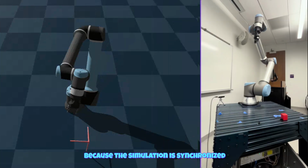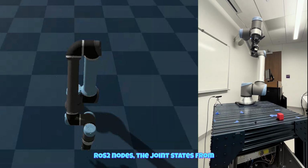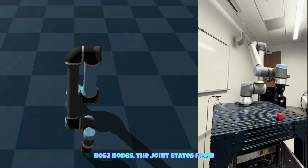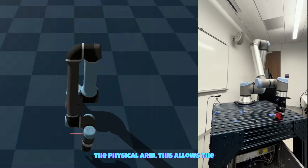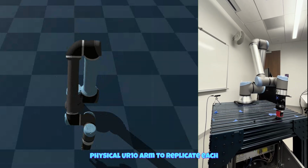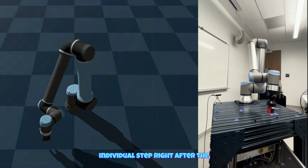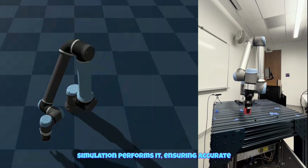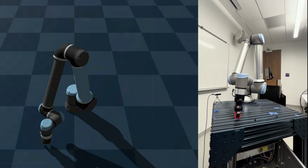Because the simulation is synchronized with the physical UR10 arm through ROS2 nodes, the joint states from the simulation are continuously sent to the physical arm. This allows the physical UR10 arm to replicate each individual step right after the simulation performs it, ensuring accurate and controlled motion throughout the entire process.